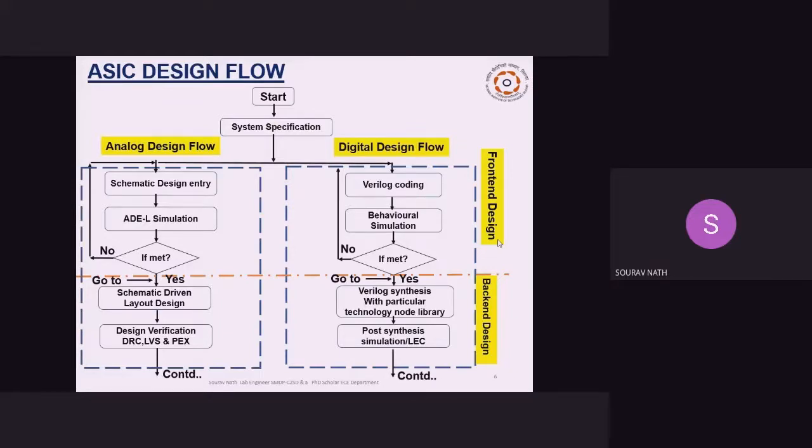Here ADE is the version of the simulation analog design environment, and the corresponding output is checked. If the output is up to the mark, then layout is generated depending upon the schematic, followed by DRC, LVS, and PEX. That is, the verification steps are done.